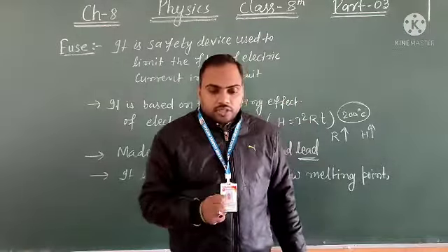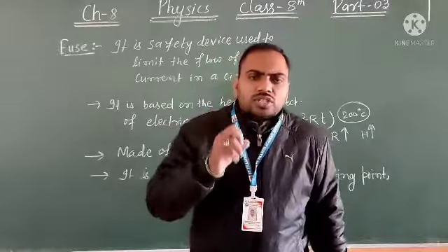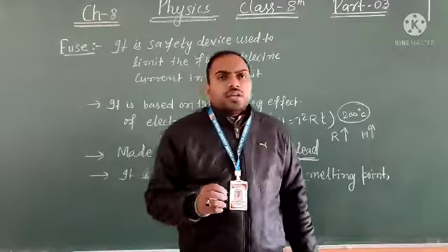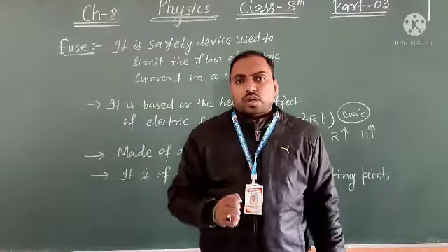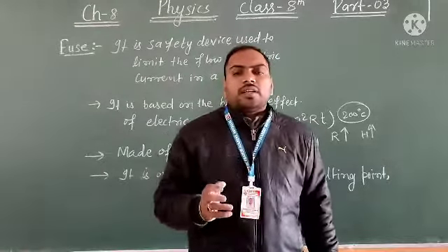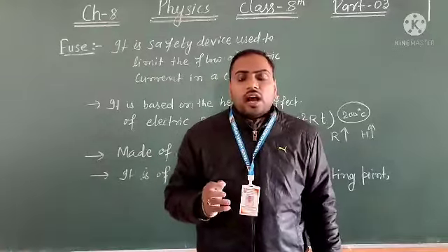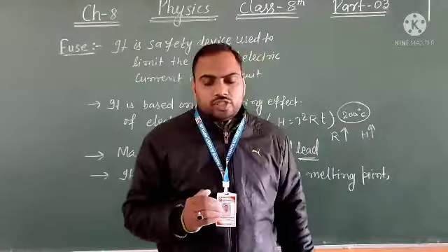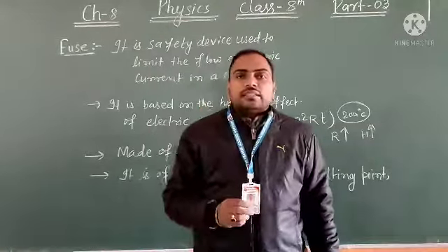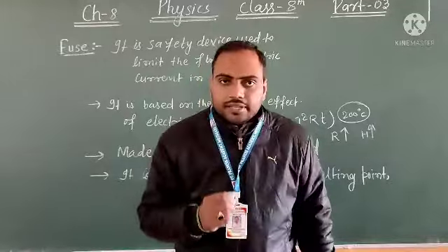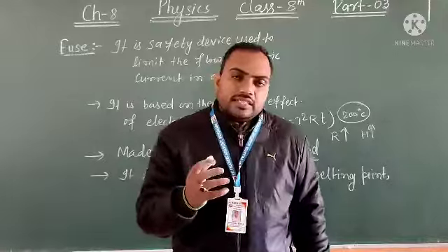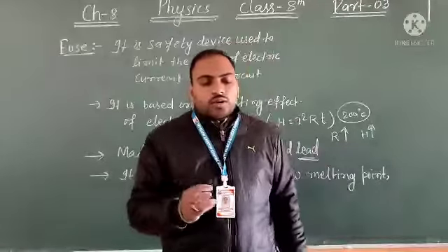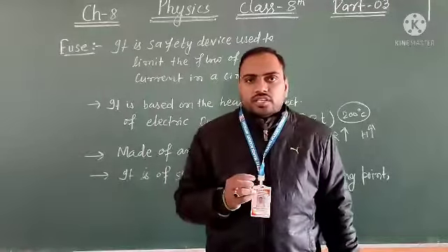Just use it. So a question arises, sir, in our homes there is 220 volt. How will the current increase drastically? Why will the current increase? There are two conditions in the circuit, understand it, due to which the current flow increases in the circuit. That is overloading and short circuiting.